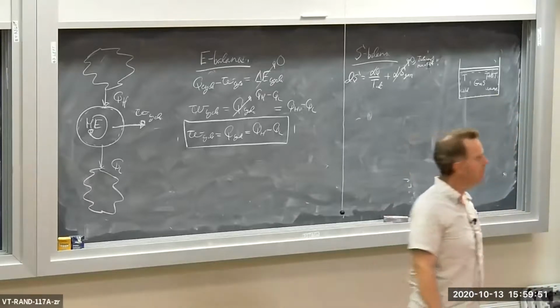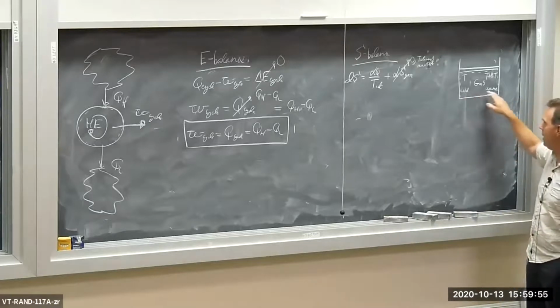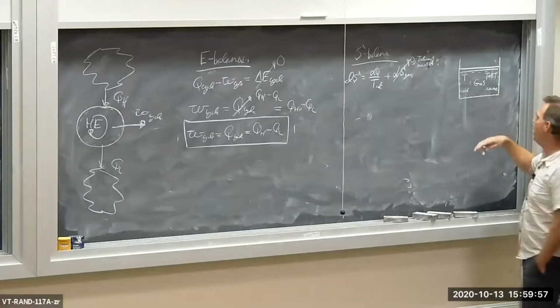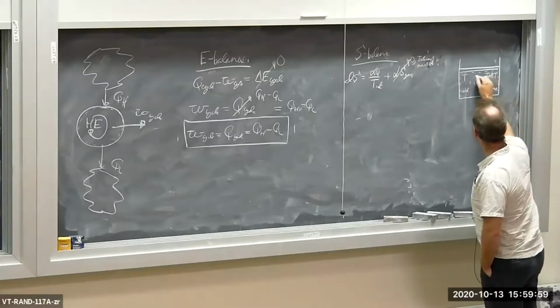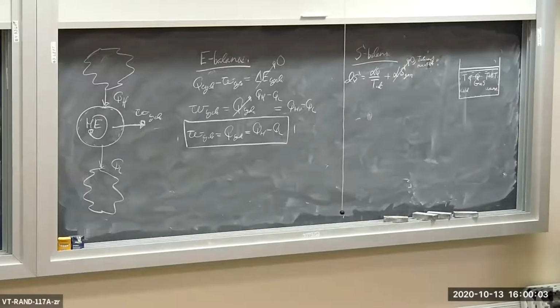What's going to happen to heat transfer inside my gas, where I have a cold side and a warm side? Well, heat is going to get transferred from hot to cold. In fact, that's heat transfer across a finite temperature difference, delta T. I can't have that. Why? Because inside the system, there's no irreversibilities.